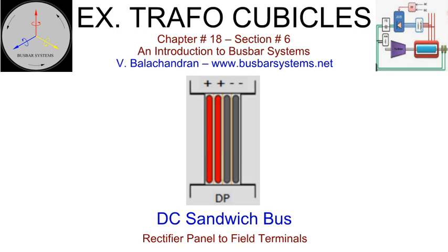The ventilation near the generator excitation connection is likely to be poor. The rectifier output will not be a pure DC but will contain harmonics. These will generate additional heat in the conductor. It will also generate additional heat due to the induced eddy current losses in the enclosure. These should be considered while sizing the conductors.